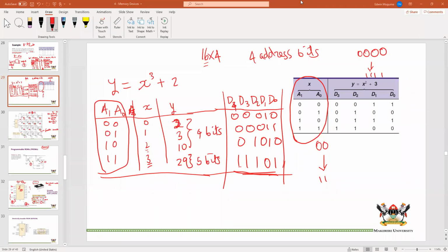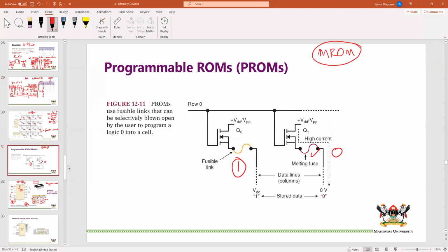Yes, on the programming, it is actually this one. When I receive my chip, obviously you're going to have another one, maybe like that. Let's say we are drawing this is VDD, and then it comes with a fusible link. Before that, the manufacturer was either blowing this for you or keeping it intact. But now, all these nodes have these fusible links, and it is up to you to blow whichever ones you want to blow and keep the others intact. If you want to keep a 0 in a certain cell, you have to blow that. If you want to keep a 1, you leave it intact.